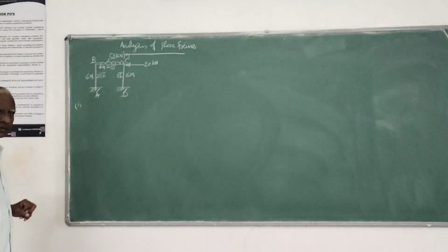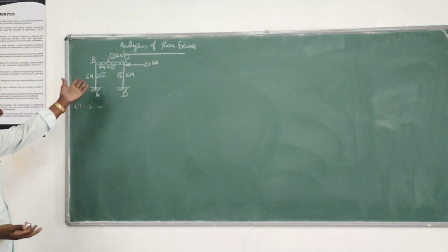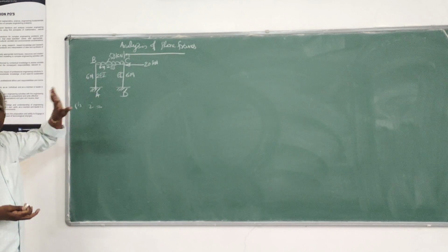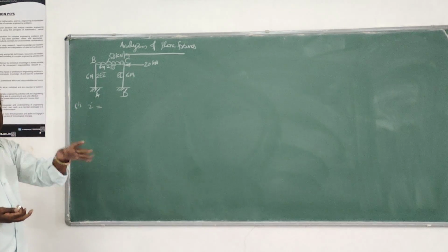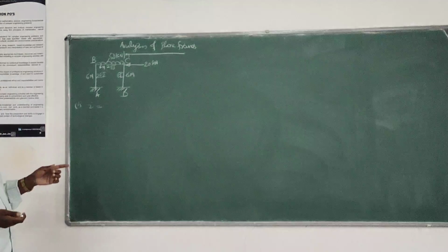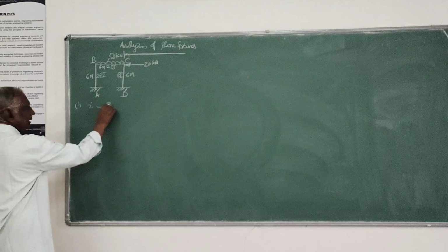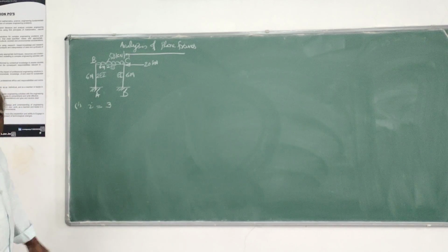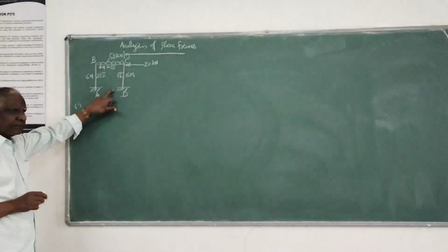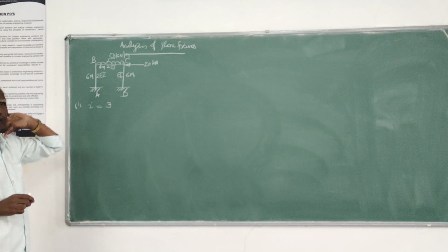So first step, as usual, find the degree of indeterminacy. Of course, I told you they are all externally indeterminate, all single story rigid plane frames. They are also externally indeterminate to the degree either 1, 2 or 3 maximum, similar to beams. Here also, since there are 2 fixed ends, the degree of external indeterminacy has to be 3. Straight away you can judge. Then you make the structure determinate by introducing 3 releases in the form of external support reactions.